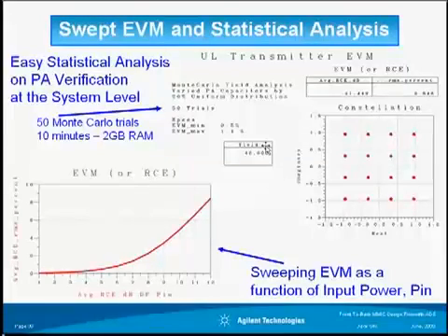And you can see the yield is shown here and the EVM. Also shown on the bottom left side is input power swept analysis for EVM. You can simulate, you can vary the input power and get the EVM for every input power. So the display basically shows the EVM versus input power.